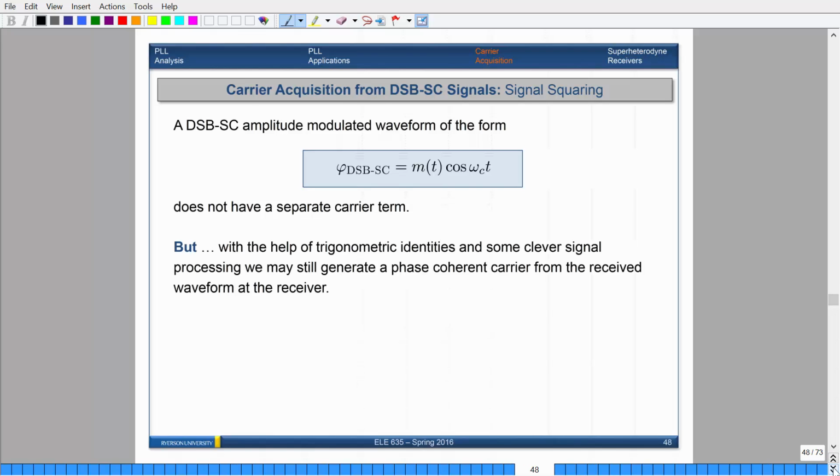Okay. So if you do a little bit of math, or if you have some extra components, you're able to extract the carrier out of that suppressed carrier signal so that you can use it and demodulate the output. Remember, what suppressed means is that in the output you do not see the actual carrier signal. But if you introduce a couple of electronics and do a little bit of smart math, you can extract what that actual carrier was to begin with.